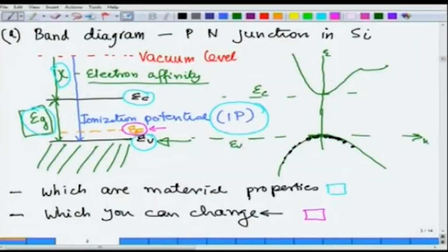And we start calling this a p-type semiconductor just because it has been doped by boron, and therefore the Fermi level has moved close to the valence band. And you know that if you dope n-type, like with phosphorus in silicon, in that case the Fermi energy moves up and goes closer to the conduction band edge, and then it is called n-type silicon.